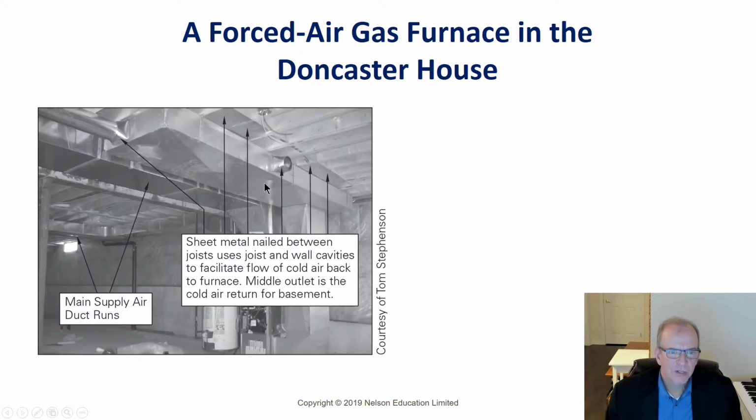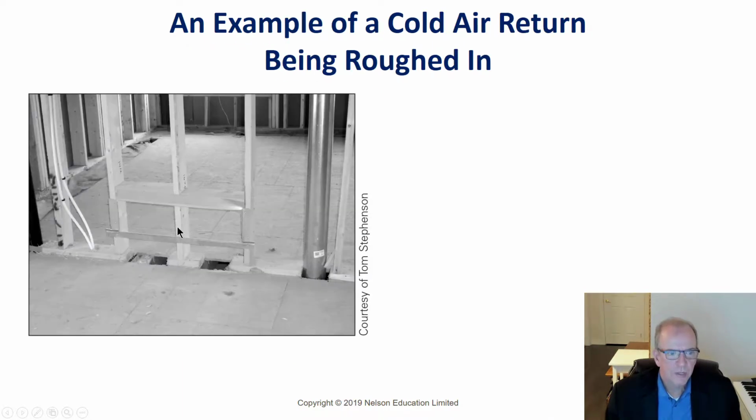Return air ducts are not done like the sealed ductwork that supplies the air to the rooms. They're just kind of closed off, so they're not as sealed the way the supply ones are. Now we tape the supply ones and make sure they're sealed very tightly. The return air pulls that back down. You're only going to be as good as the effective opening size, by the way, if you've got big openings here but smaller openings there. So I don't know if that's exactly sized right the way they did that.